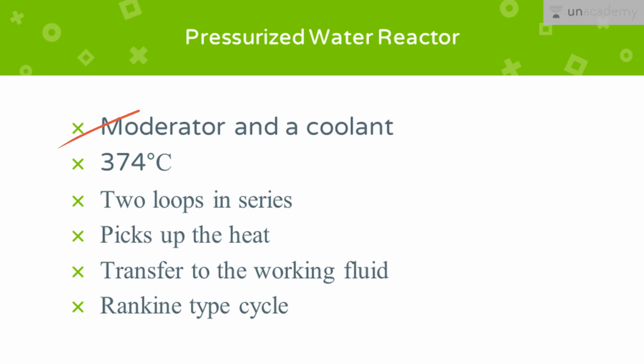The most important limitation on a pressurized water reactor is the critical temperature of water, that is 374 degrees centigrade. This is the maximal possible temperature of the coolant in the reactor, and in practice it is considerably less, possibly about 300 degrees centigrade, to allow a margin of safety.